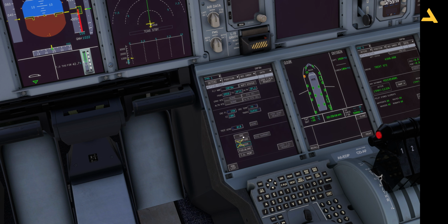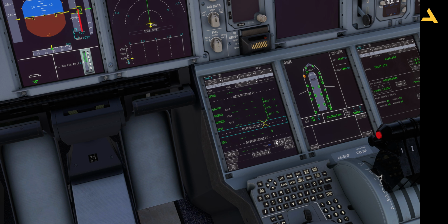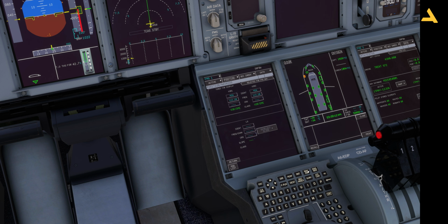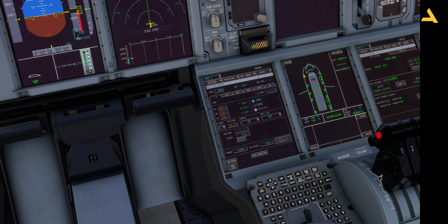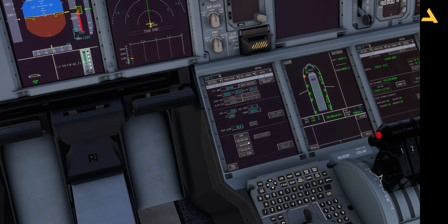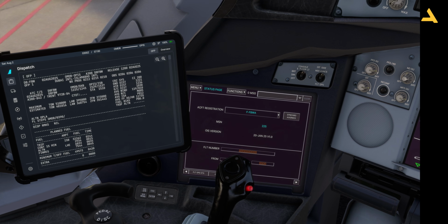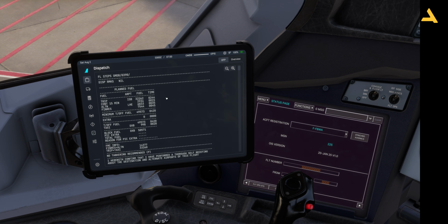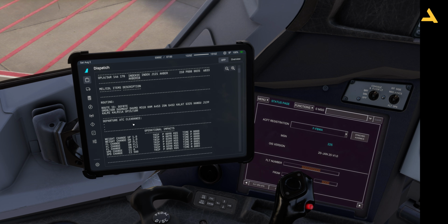And you have to actually then now configure the FMS as per this sequence. And one more thing, you can just scroll through different options over here on the FMS by using these buttons. So let's say you can look at the flight plan, initialization, and nav aids, and performance and stuff like this. So I can go back to this page, and now I have to set the departure and the arrival. So for the departure, if you go over here, scroll down, you will see this runway is appearing over here, which is 30 right for Dubai, and DAVMO 4F.